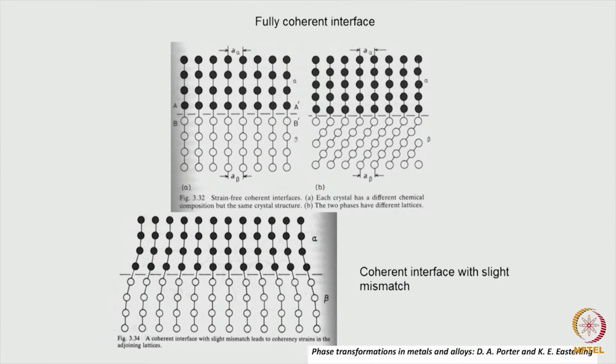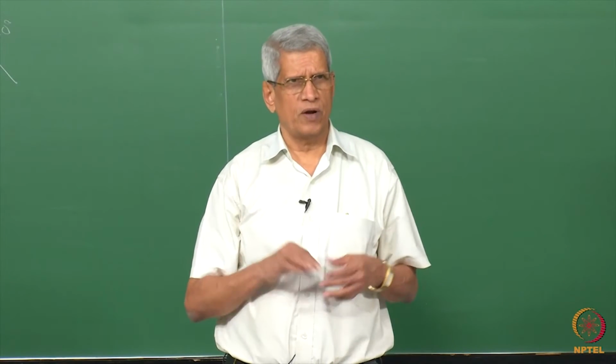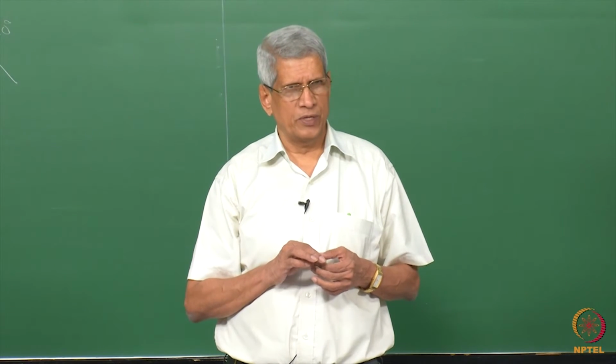So far, what we considered was essentially with respect to a single phase, right? That's small angle boundaries, high angle boundaries and special boundaries. These are all the types of boundaries, and depending upon the energy between the various types of boundaries, there is an angle which will be made between the boundaries.